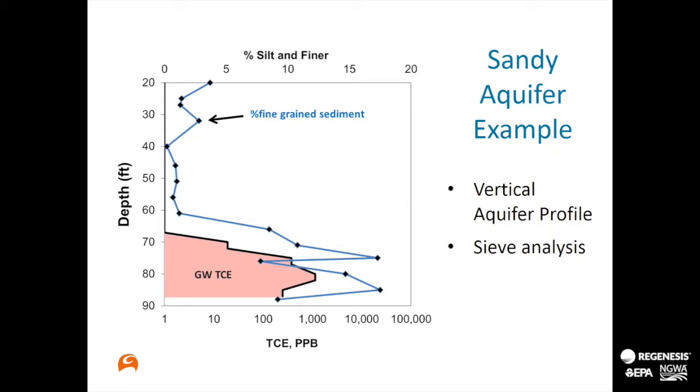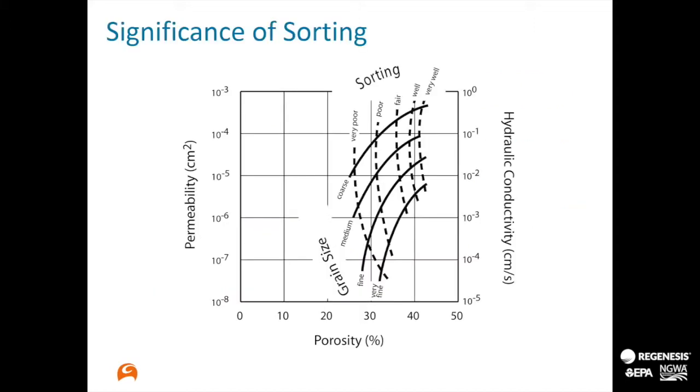So I can't overemphasize the significance of sorting. I think, Rick, for your Battelle talk, you say leave your USCS classification at the door. Leave it at school, wherever you learned it. It belongs in the dustbin. We really need to be guiding our field geologists to record the percent sand, silts, clays, and so forth, so that we can do the type of reconstructions that Rick is doing, and not just have them write down ML or CL or whatever.